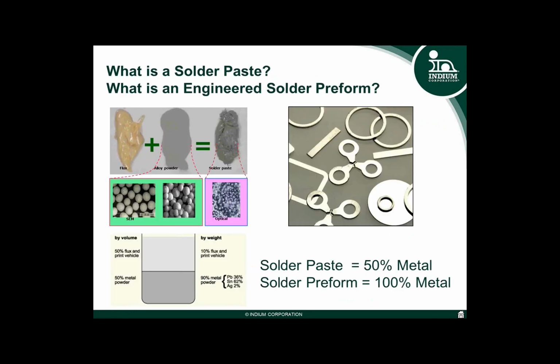Briefly bringing you back into the realms of maybe solder paste that lots of the audience are familiar with. So solder paste in itself is a more modern way of making the interconnection between the PCBA and a component. In this case, a solder paste is roughly 50% by volume a flux system, which is used as the medium to contain the solder powder or the solder volume. These are usually blended together to make a convenient paste that you can then take through a stencil print process.